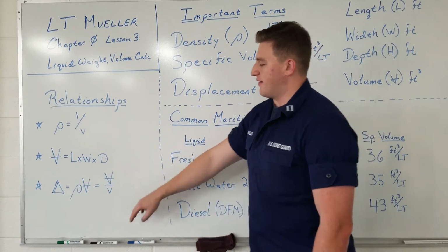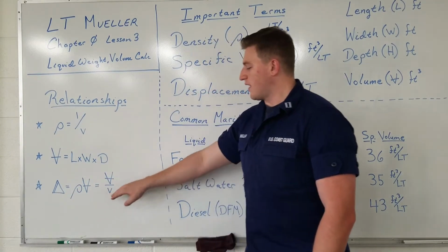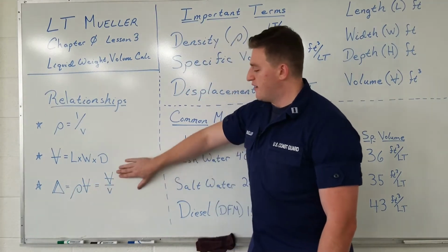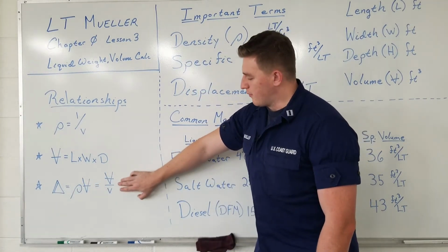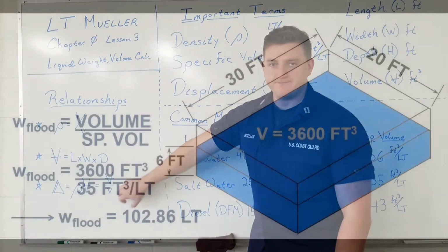The next relationship we have is displacement equals density times volume, or as we'll typically use in this course, displacement equals volume of a compartment, or the volume of flooding water, divided by the specific volume of that fluid.